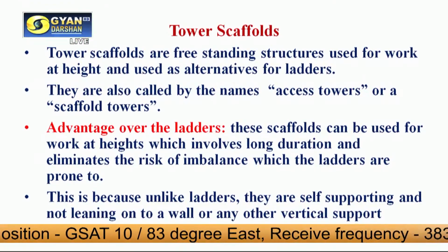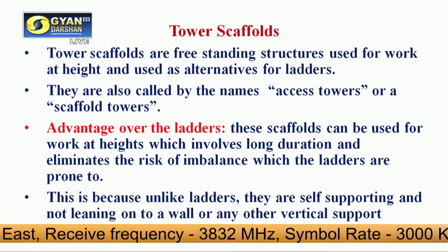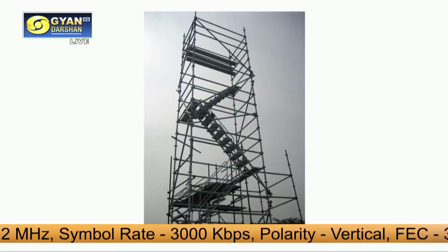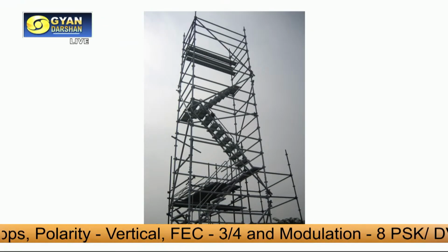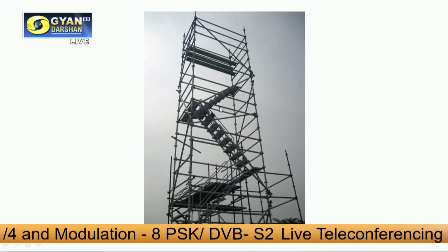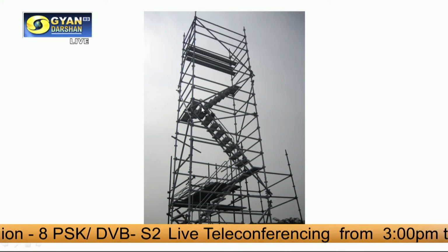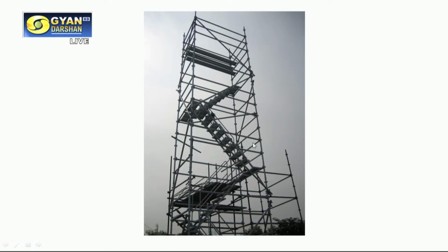This is because, unlike the ladders, they are self-supporting and not leaning to the wall or any other vertical support system. This is the picture. Basically, you can see how this tower scaffold looks like. So here you see that access is provided to climb up in this tower scaffold. So these stairs are provided there. So this is how this tower scaffold looks like.